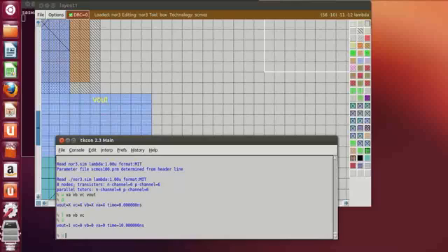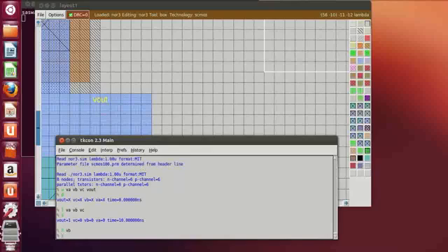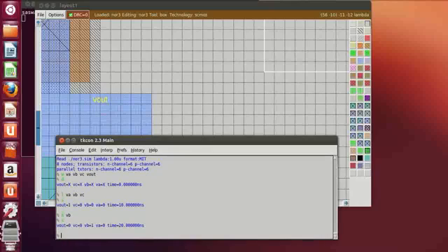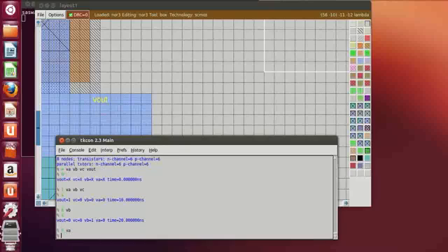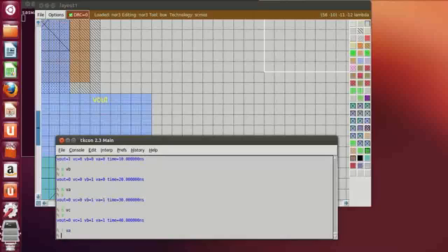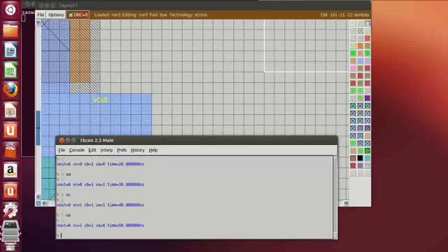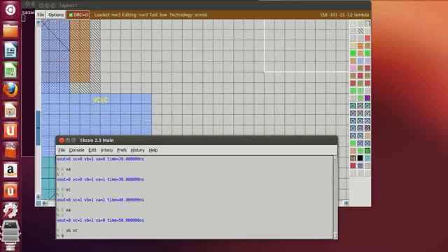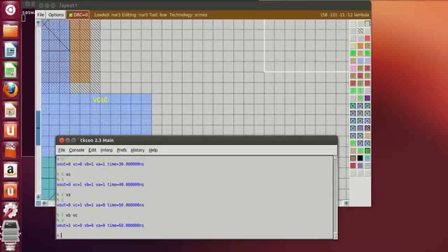So let me give high value to VB, suppose, then S will get 0. High value to VA, then give a step function, again it's 0. High value to VC, 0. If I give low value to VA and then give a step function, still 0. Only in a case where all the three are 0, we get output as 1.